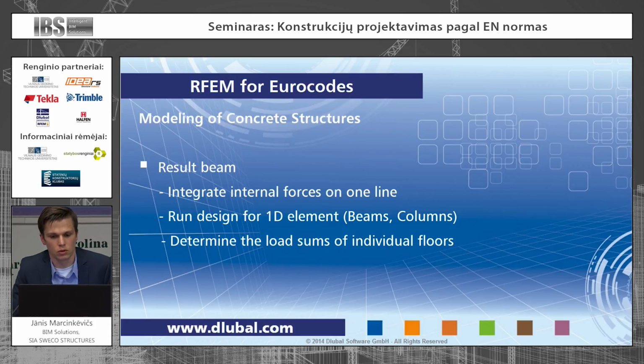You cannot just calculate it as a bended element. To some extent, of course, you can, but with precast concrete, where there are pin connections on the top and on the bottom, the main criterion will be buckling anyhow. So you must calculate that. So what to do with the wall where you have the surface and some concentration of stresses on the corners? How to deal with those?